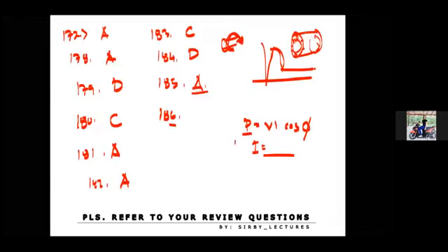For letter D, if you install a frequency inverter device, you're just changing the speed, but you're not changing the rotation. For the option to increase the voltage source, of course, that would damage the electric motor. If the motor is specified to run at 220, then you shouldn't increase the voltage source. So the best answer here is letter C.